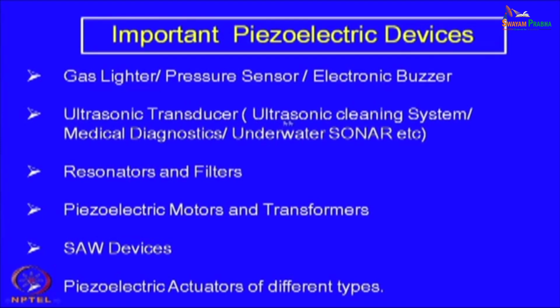Of course, in cleaning systems you do not need any feedback or any kind of sensor, it just generates the wave or the ultrasonic beam. But in medical diagnostics or underwater sonar, we need both. You need a source, and then the reflected wave must be detected, and its characteristics, both in intensity and the phase lag, have to be measured. Now, in medical diagnostics, as you know, we always use ultrasound techniques.